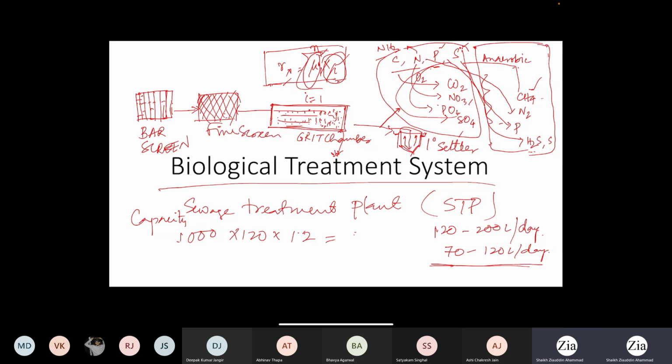Liquid will try to go up, whereas solid material, due to gravity, will try to settle. Because of the settling velocity, if the settling velocity of the particle is more than the rising velocity of the liquid, then the particle will settle, and through the discharge line you can get all settled particles from the settler.